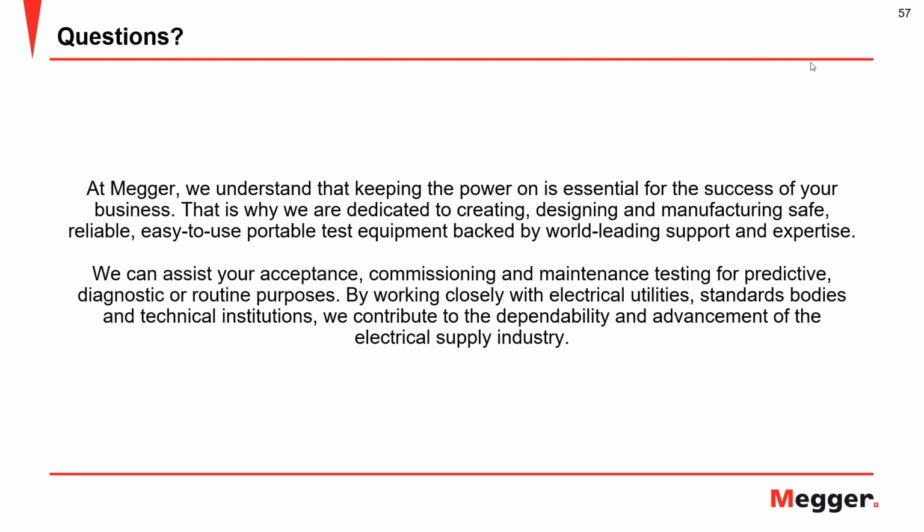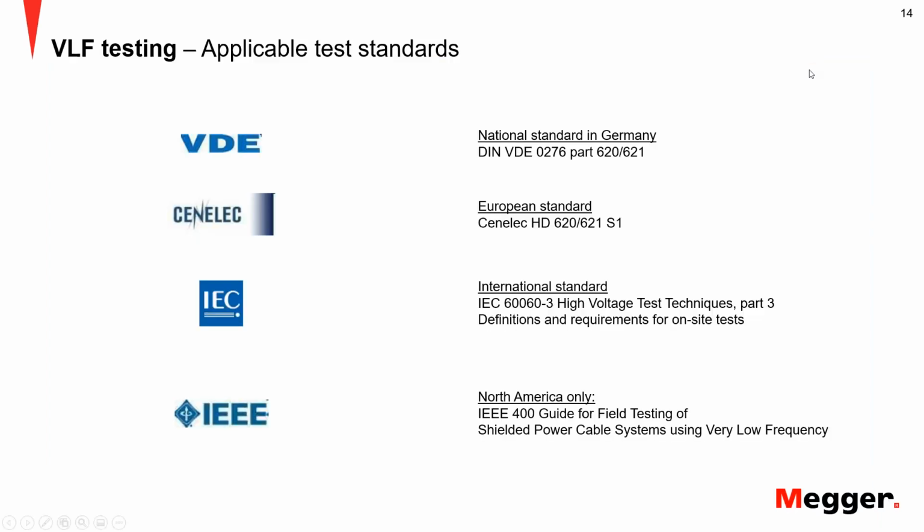On all low voltage cables, to be precise, that have no shield, and typically low voltage cables have no shield, you cannot use any of these test methods, whether it's partial discharge or any dielectric test methods, because you cannot establish a defined electrical field. So unfortunately, for typical low voltage cables, you cannot do any condition assessment using any of these methods. And there are basically no other methods that can be applied for low voltage cables.